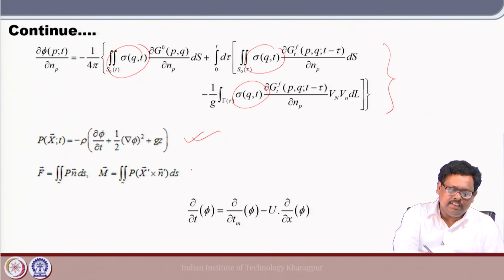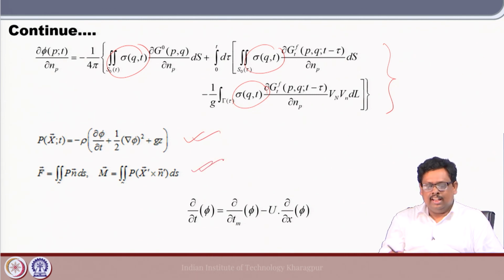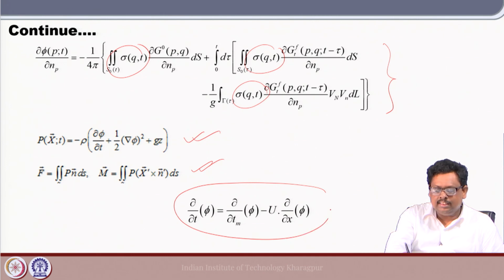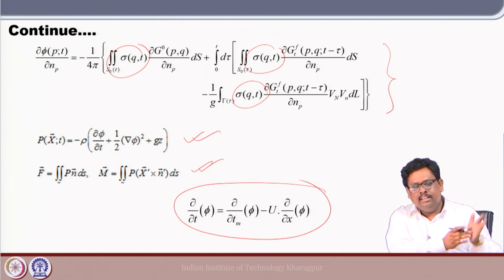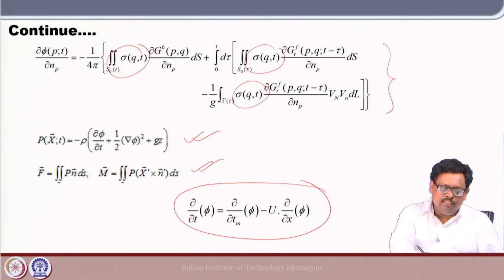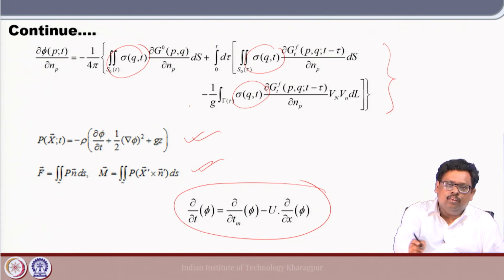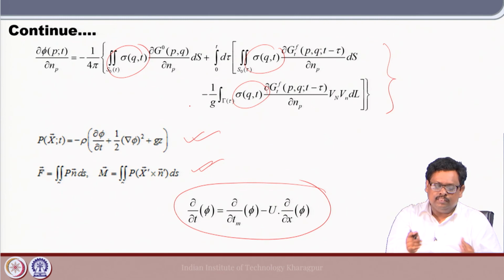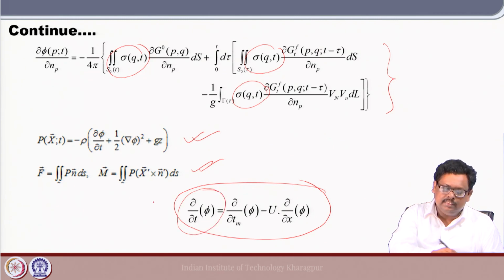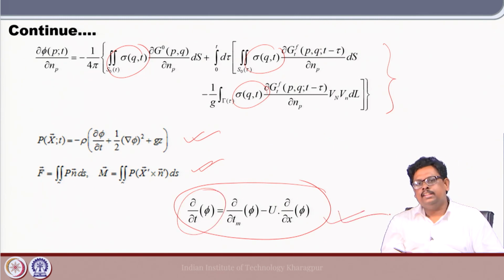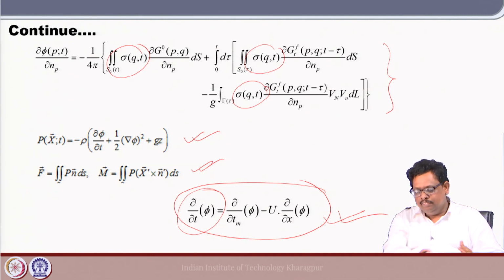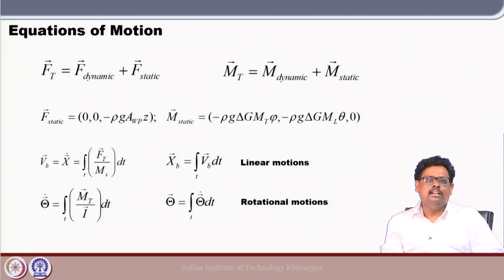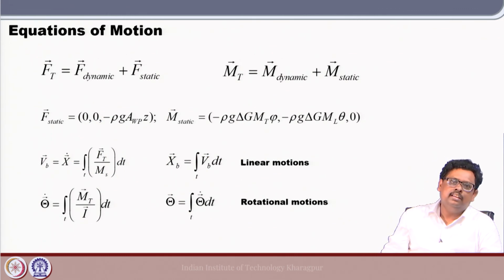When I get the pressure, I can get the force, and here I am making the transformation. We already discussed in our previous classes in strip theory how all this is formulated in the body fixed system. So, I have to return back to the earth fixed system. So, I do this operation to change the pressure from the body fixed system to the earth fixed system, and then when it is done, I use the equation of motion.